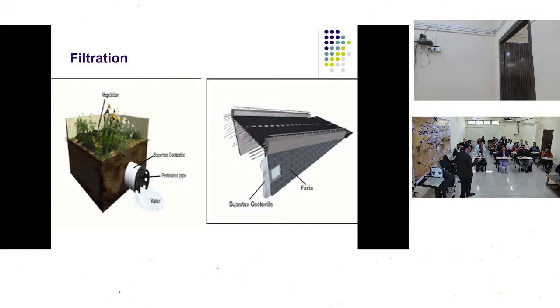And so my fill is in a relatively better condition of saturation. I'll say it will be in a semi-saturated or dry condition. Thereby we will have higher shear strength and the fill will be stable. Problems also come at times if we do not design this aspect in the correct manner. The geotextile will get clogged over a period of time, and then again I will have the problem of the water not being removed.